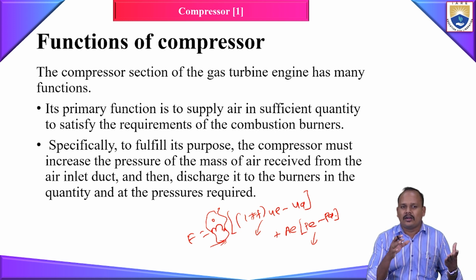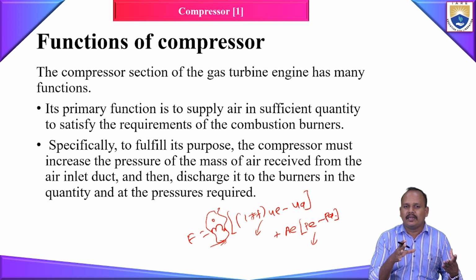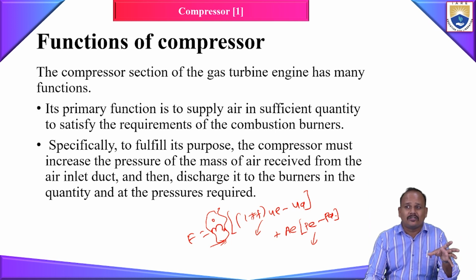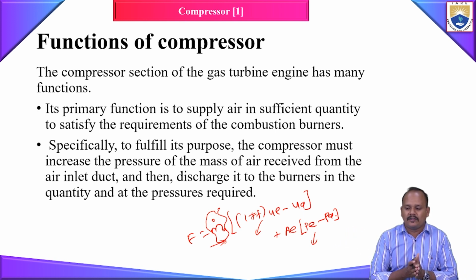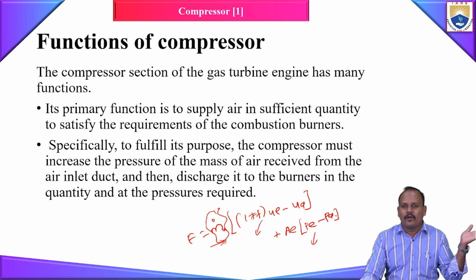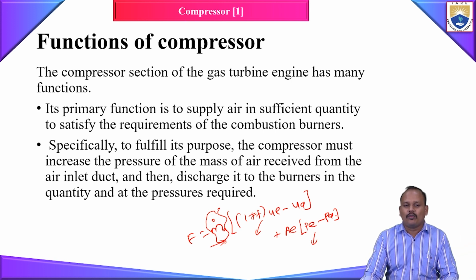See your compressor, let's say in the static condition, when I start my compressor, what is going to happen? It is going to create suction. By creating the suction, it is sucking a huge amount of airflow from outside and compressing it. Basically, it is reducing the volume of your fluid and increasing the pressure. If I don't have the compressor, your flow will just simply enter, and the volume of fluid passing through your combustion engine will be limited. But the volume or mass flow rate is very important because it is directly proportional to how much thrust we are producing.